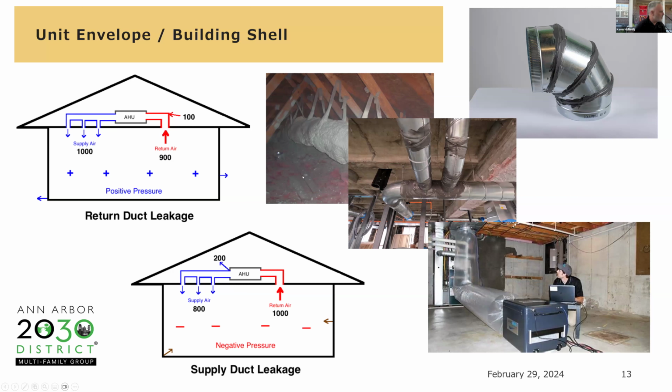Here are some ways to seal a duct up. If you have ducts in an unconditioned attic, I'm a big fan of using closed cell spray foam to insulate and air seal that duct system all the way down to the ceiling plane.